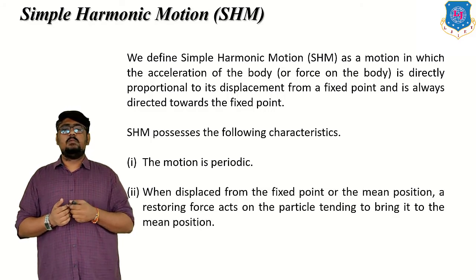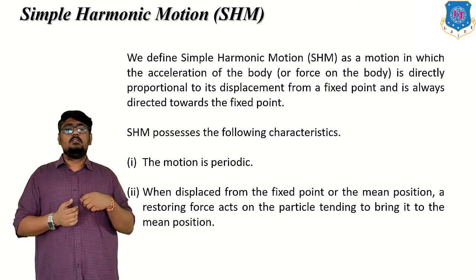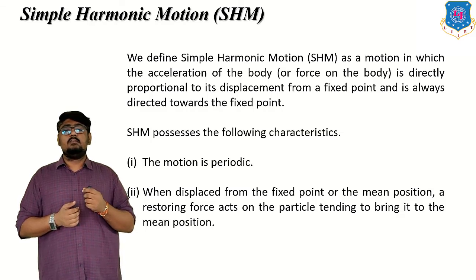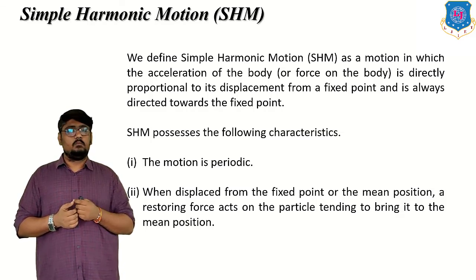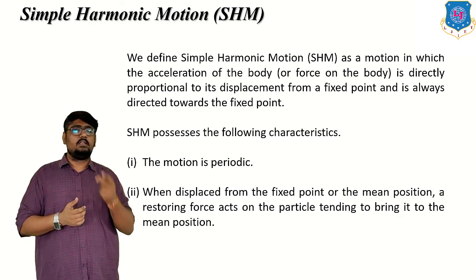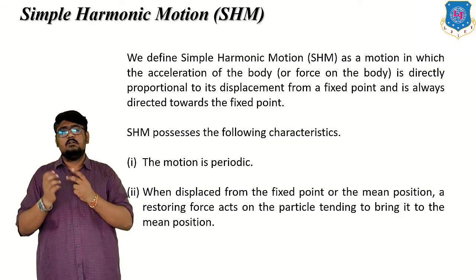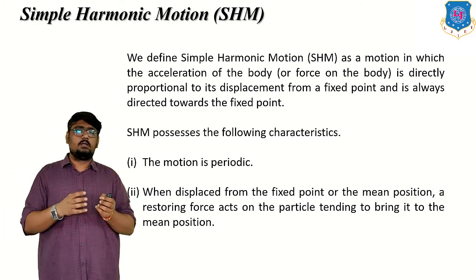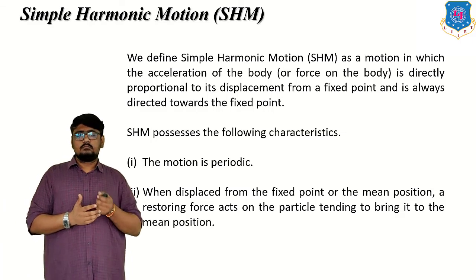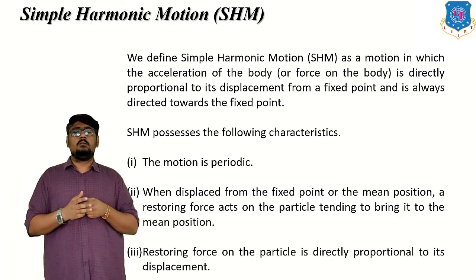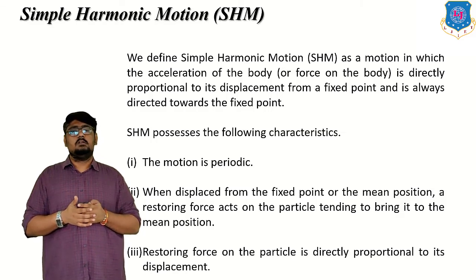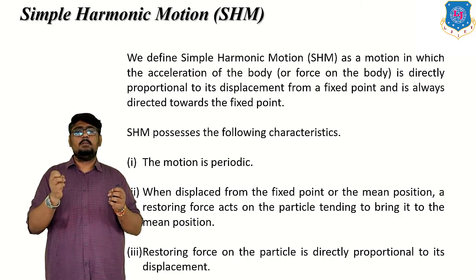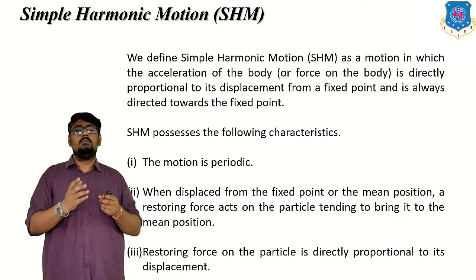Another one is that when displaced from the fixed point or the mean position, a restoring force acts on the particle and tends to bring it back to the mean position. Whenever it is offset, a restoring force is created inside and it tends to bring the particle back to its mean position. The third one is that the restoring force on the particle is directly proportional to the displacement. Whatever amount of displacement is made, depending on that, the restoring force will be generated.